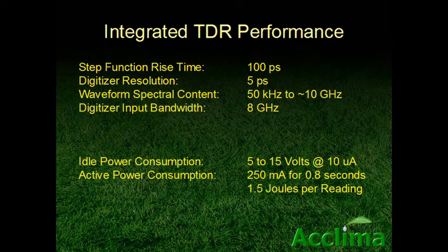The reported permittivity and water content readings are immune to EC up to the point at which the signal is attenuated to where it can no longer be received. The device has an SDI-12 interface and runs on any voltage between 5 and 15 volts, drawing 10 microamps in its idle state. The active state current draw is 250 milliamps for 800 milliseconds.